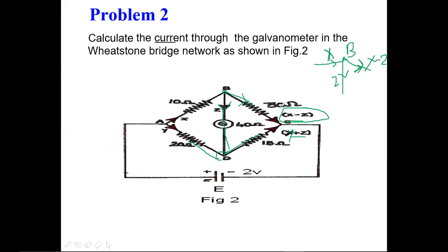That's the procedure to identify the nodes. Here he assumed only three currents, X, Y, Z. He did not assume four currents, because here there are only three loops, one, two, three. That is the reason he should assume only three currents. Those currents only he utilized for naming the 30 ohms branch and 15 ohms branch.